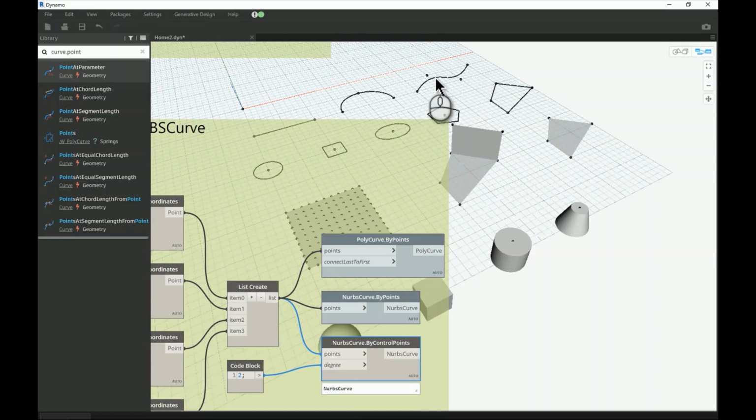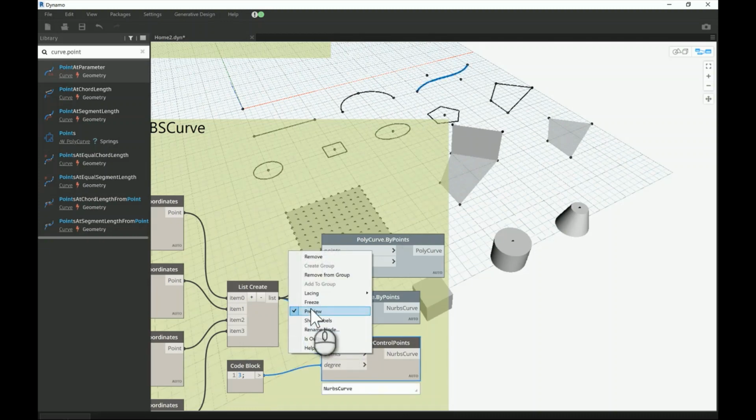The others act as controlling points, and with a degree parameter, if you change that, I think it's just between 1 and 3 as values, not much of an option, you get less curvature, less close to those points or closer to those points, to create this type of control point NURBS, which is, by the way, a different structure from the normal curves.